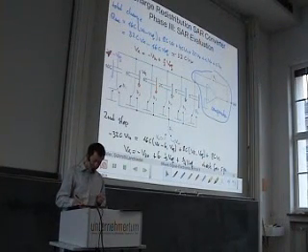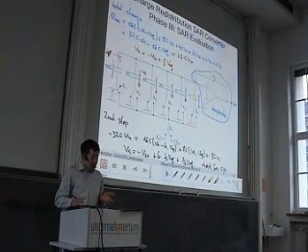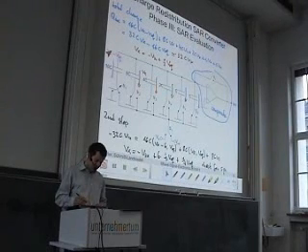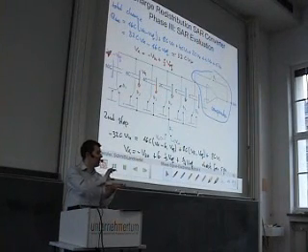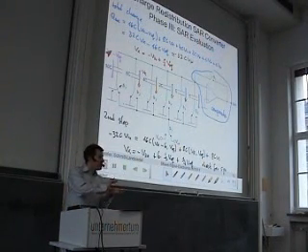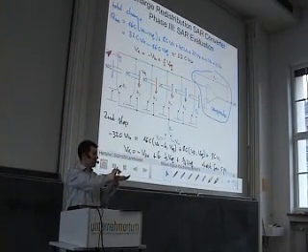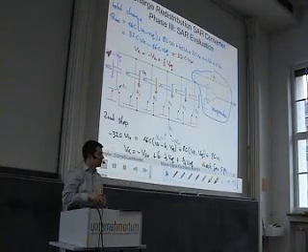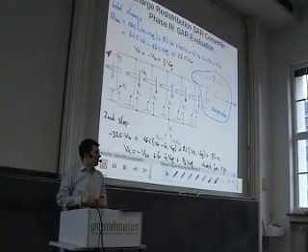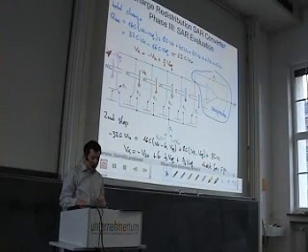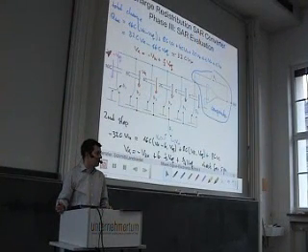And if we toggle the switch towards Vref, then we raise the bottom of this cap. So you can also imagine this as a kind of charge pumping. Here all the bottom nodes are connected to ground and the caps are charged. And now you push up one because you put the bottom to Vref. And so the charge that is due to this push-up is placed on the other caps in order to equalize this, and then we end up with the respective Vx potential that is then compared against the zero.